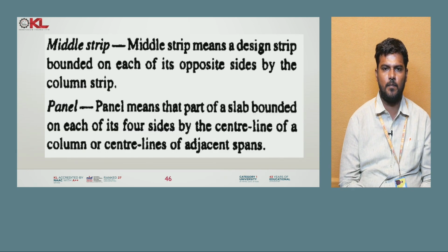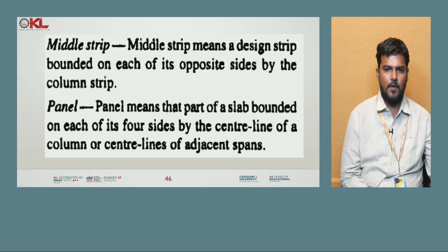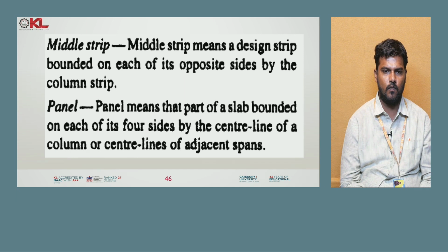Next one is the middle strip. Middle strip means a design strip bounded on each of its opposite sides by the column strip. Panel means that part of the slab bounded on each of its four sides by the center lines of the columns or center lines of adjacent spans.